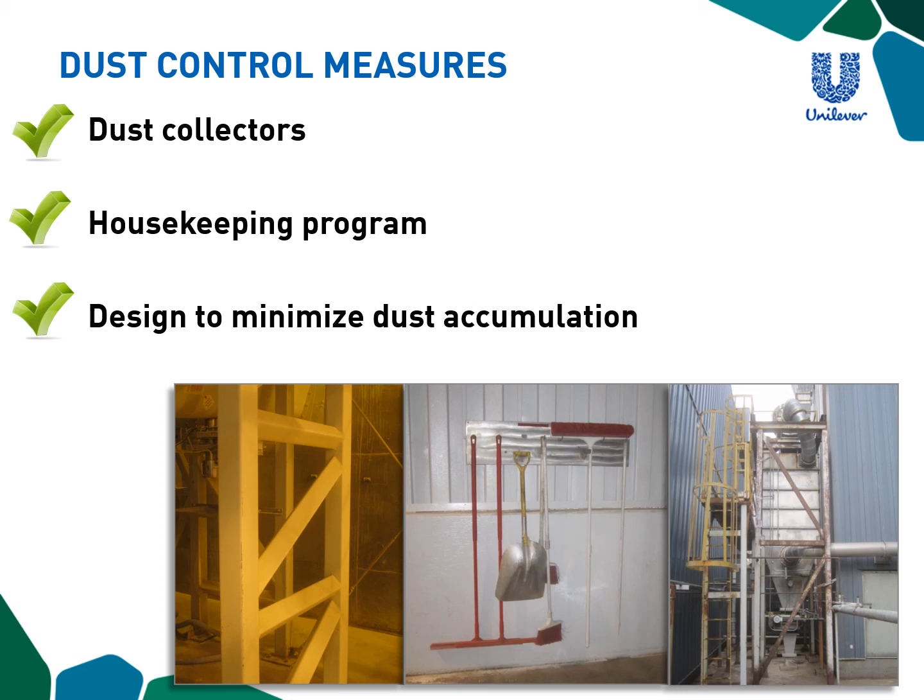We also have engineering designs to help minimize dust accumulation, such as in the picture on the left there. Some of our racking in the warehouse, the steel support bars are actually at a 45-degree angle, so dust does not accumulate on those surfaces, but rather collects on the ground where it can be cleaned up more easily.